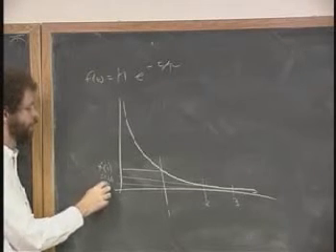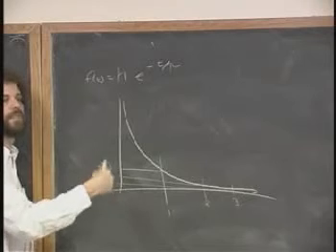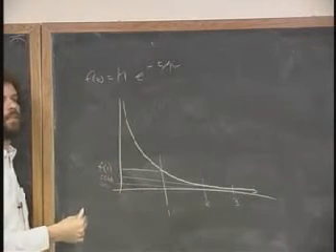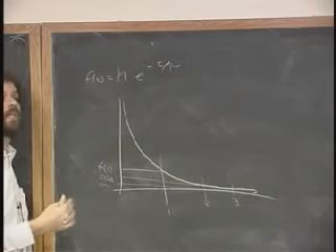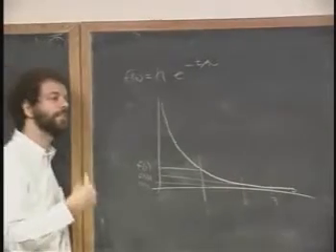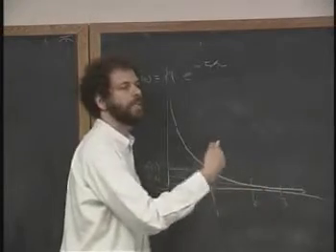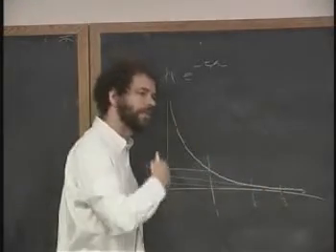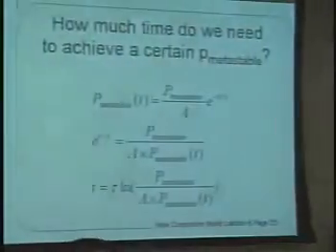F of 1 over 4. So it's sort of geometrically decreasing every second of time that goes by. Now you guys all know how fast a geometric series gets big. Something that geometrically decreases gets small very, very fast. So every second that goes by, we cut down again the probability that it's metastable. And so that goes down very, very fast.